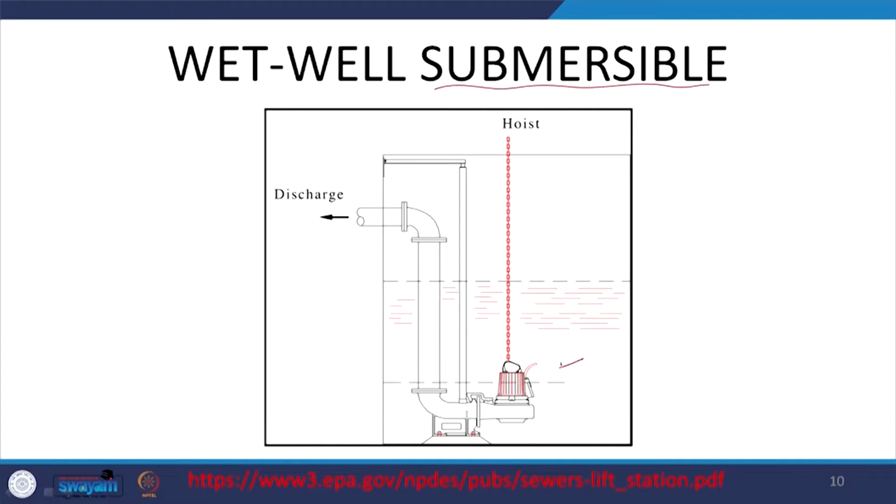That is what you see here, and whenever required it is hoisted up. Here maintenance typically seems to be low, but whenever maintenance is required, that is going to be a concern. One aspect is the costs seem to be relatively less with wet well submersible pump systems, and that is what at least we see in India most of the time now. So, that is something to keep in mind.